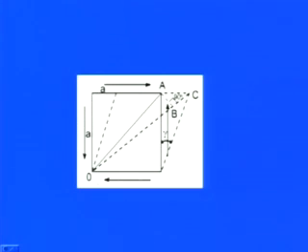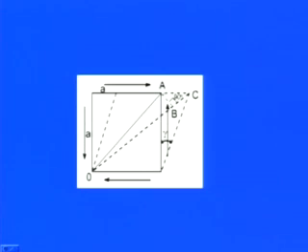So, this point O and this point, this is the initial position, and due to the shear stresses there is a distortion, and then this point A, which is at the extreme corner, so OA is nothing but now my diagonal. This diagonal is now shifted from A to C. So, we have the new diagonal OC, and earlier this was OA.